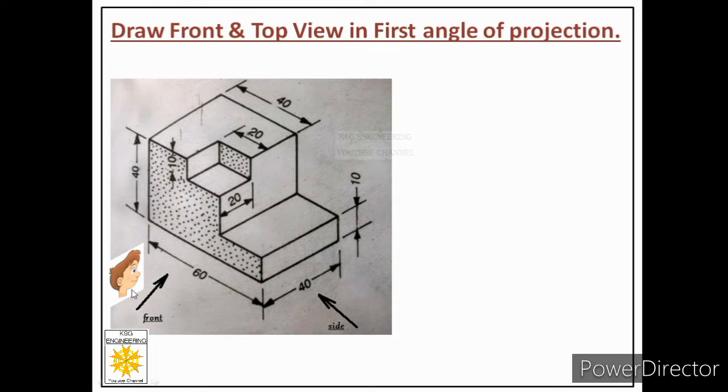Okay, so now the first step is we should see how many total faces there are in this object. So over here 8 faces are marked. Apart from these 8 faces, we have the left side face, the rear face and the bottom face. But you can see the bottom face and the left side face, these two faces are perpendicular to the plane of projection.